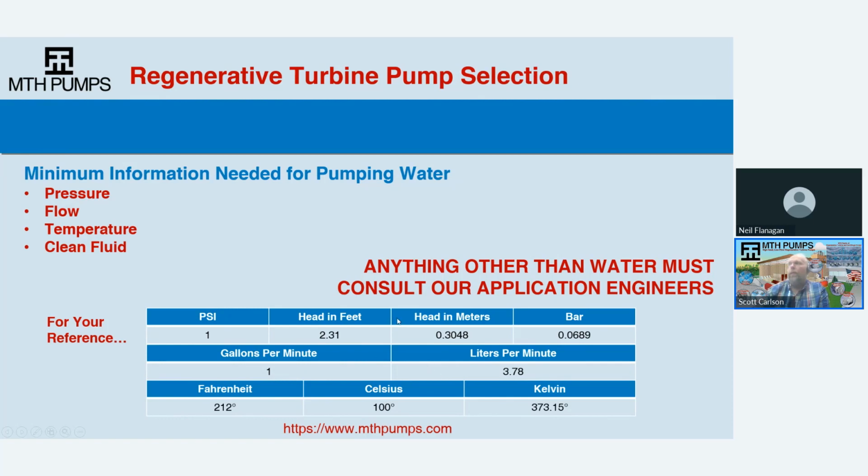And then the most important parts of any kind of pump selection that you would need are the pressure, the flow, the temperature, and the fluid has to be clean. And if there's any other conditions to what you're pumping other than water, you really need to consult one of our application engineers, make sure all the materials are compatible, make sure there's not going to be some strange effects as temperature changes, and so on and so forth.